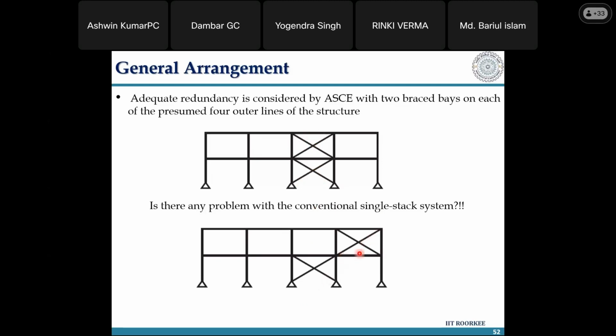Now, one problem with staggered bracing is that you may think the lateral force resisting system is not continuous. The in-plane continuity is getting disturbed, an irregularity case that we have in 1893. This is violating the in-plane regularity condition. But what advantage the staggered arrangement has is this: if you have the braces arranged along one particular bay over the height, the foundation forces are going to increase more here.